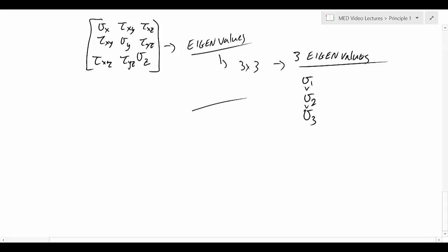So what we've covered so far is the types of loading, the stress we can get from those types of loading, and how to find the absolute maximum at a particular point. Recall, where things fail, it's going to fail at a particular location, so we need to figure out where that location of maximum stress is, figure out the orientation such that we know the absolute maximum shear stress or the principal stresses, and from there we can actually start applying our failure theories.